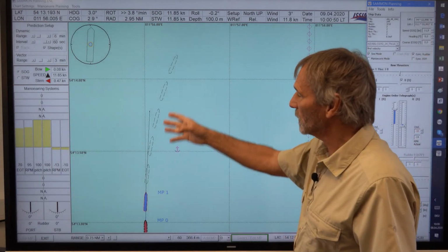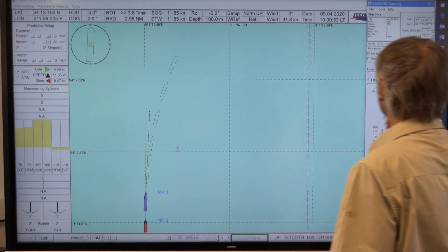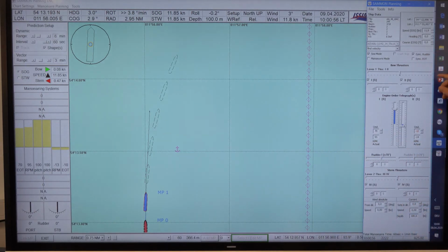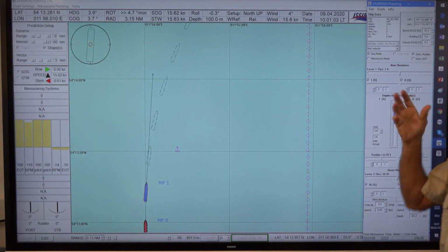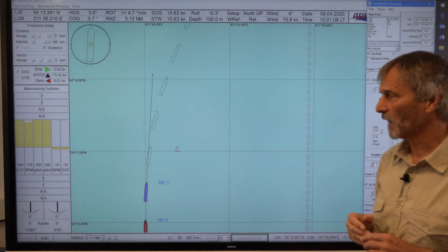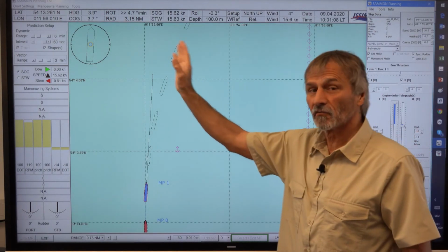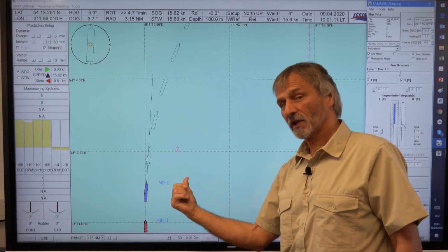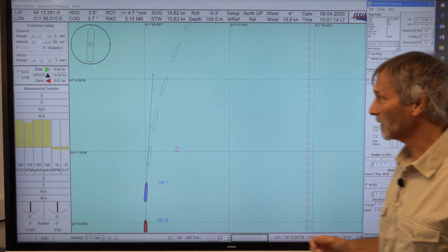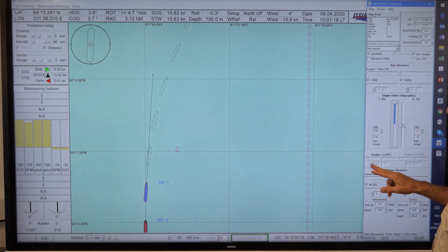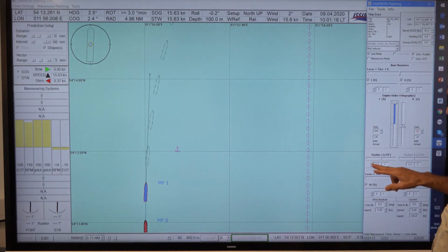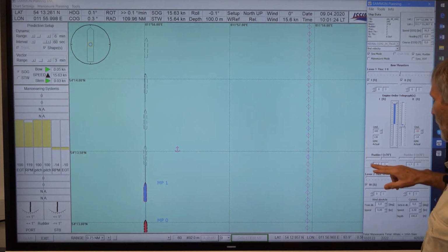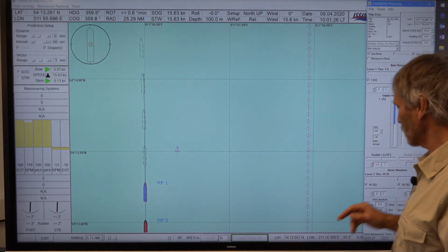So you see immediately, okay, the ship is getting slower. It's getting now 11.9 knots, but if I increase this engine to full ahead, we are on 16.3, so it's nearly the same as we had before. We had to adjust the rudder a little bit because this starboard engine is braking, so we have to adjust the rudder a little bit to the starboard side. Let's say this is 1 degree. Okay, playing around a little bit. So this is where the ship is going straight.